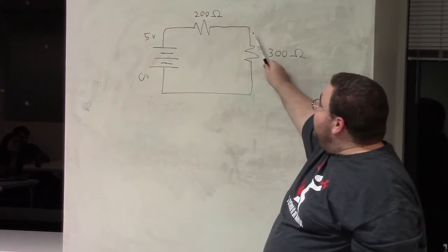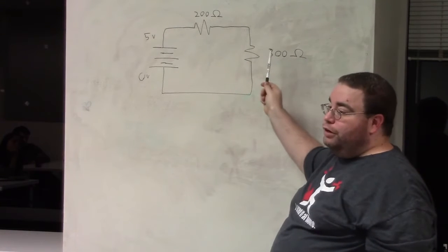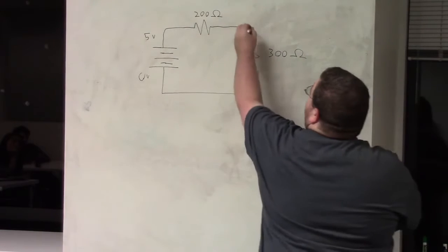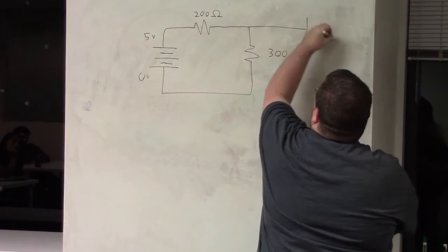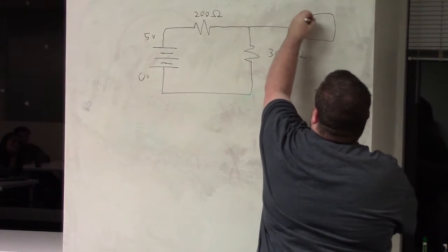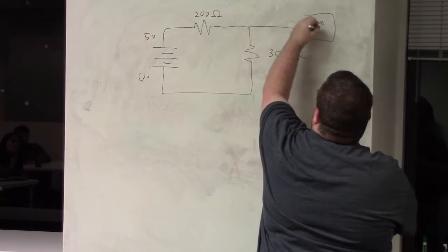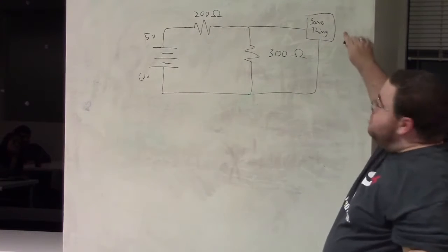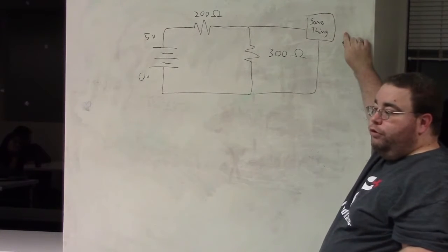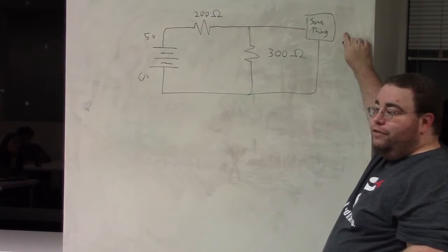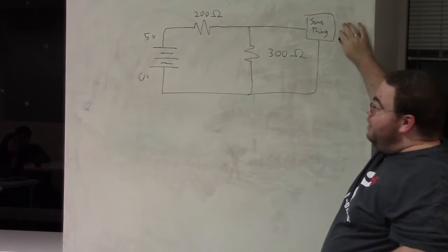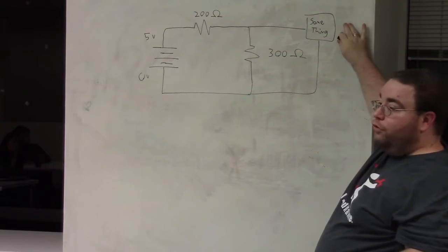So this is actually a really handy circuit, because what this will do is translate. If you've got a chip or something that needs 3.3 volts, and all you've got is a pack of 4 AAs or a USB plug or something that provides 5 volts, this is one way to get 3 volts out of it.